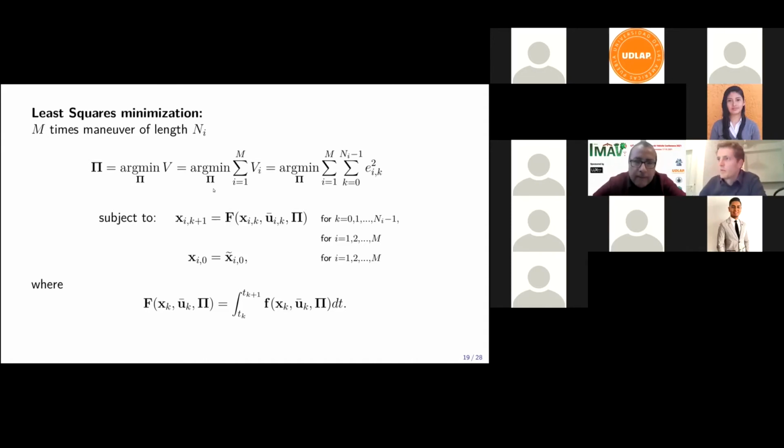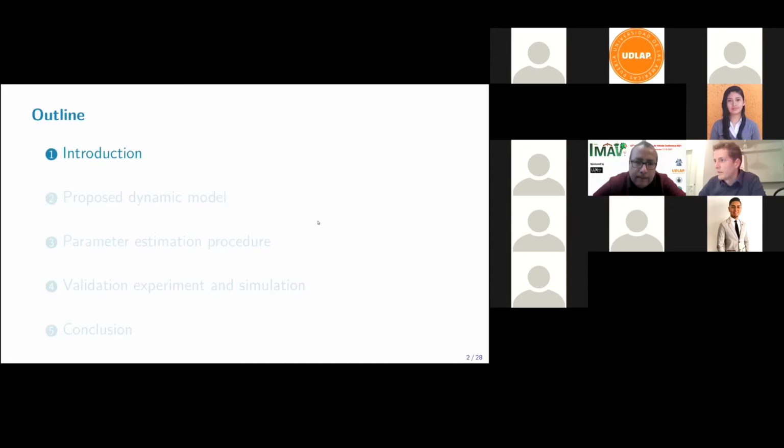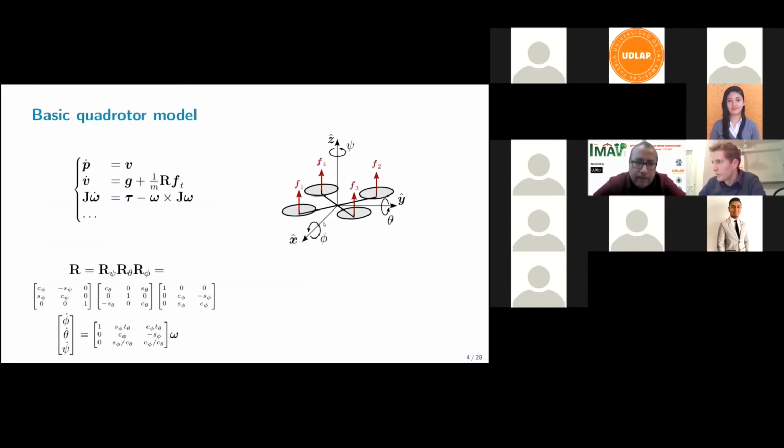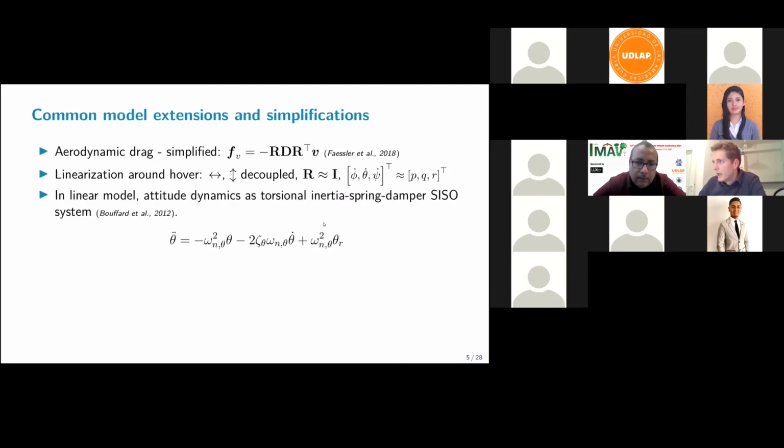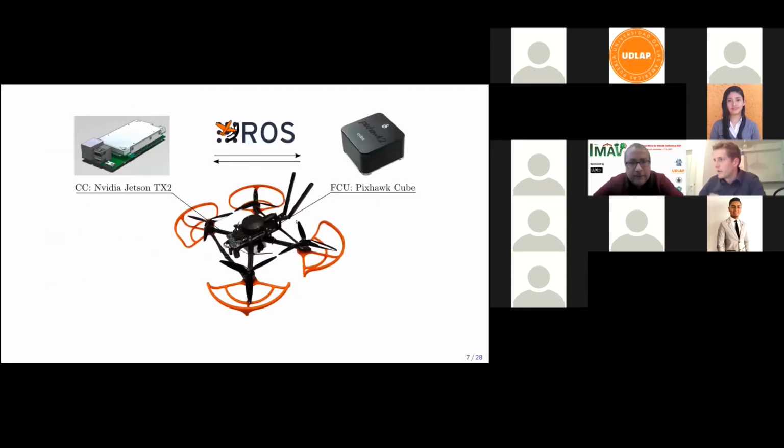Yeah, sure. So basically, our setup has this low-level flight controller, which is running ArduCopter firmware. When you switch a mode, we operate in guided mode, and in guided mode, this companion computer has the authority and can send input commands. But once we switch the flight mode to stabilize mode, then the control comes from a human pilot, actually.